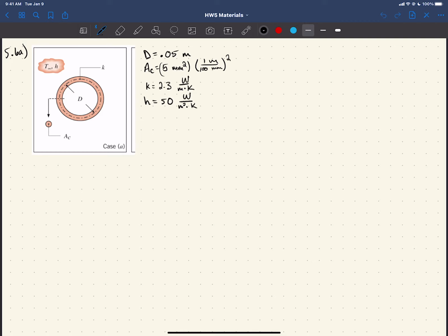So let's start by just saying, here, our Biot number is going to be h L sub c over k. This is not the first time that this has come up. He's mentioned it before, usually when we were talking about thermal resistances, because this is actually a ratio of your conductive resistance over your convective resistance, right?